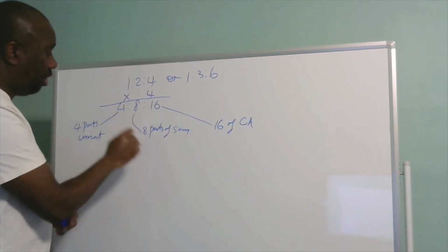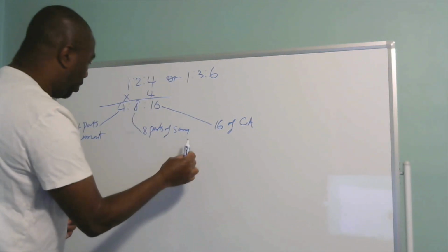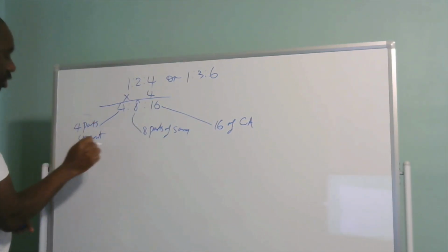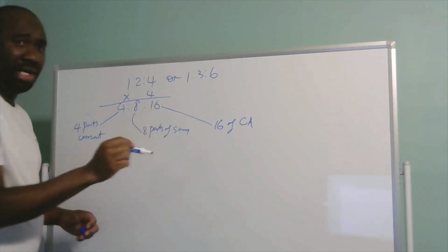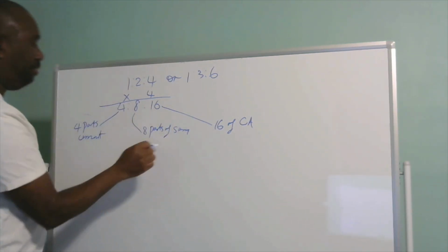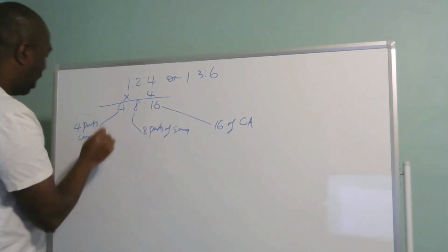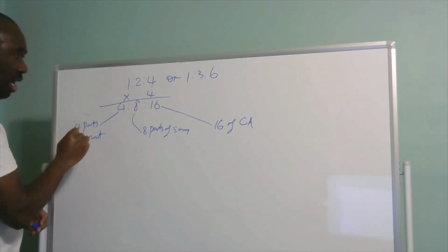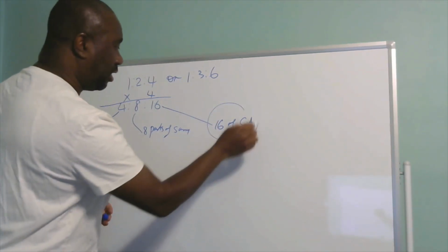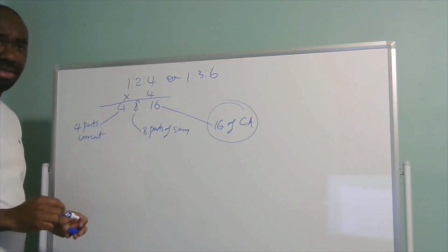When you run on your 8 barrels of sand and you level it out, then you run on your 4 barrels of cement. So what we call sweeten back in the days, you mix up your sand and your cement together and then you level that out and then you run on your 16 barrels of coarse aggregate, right?